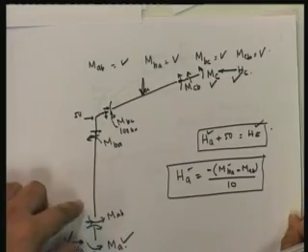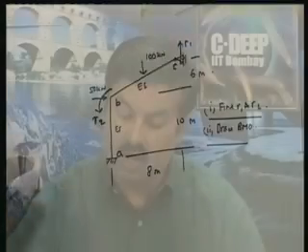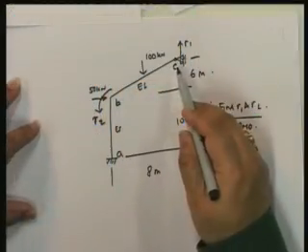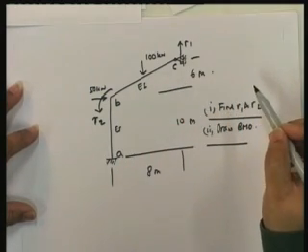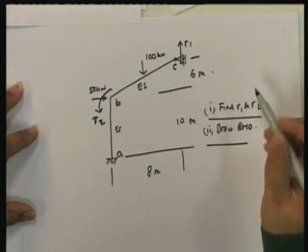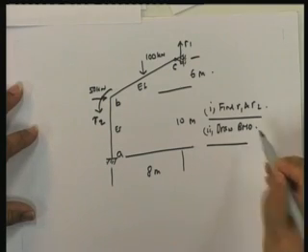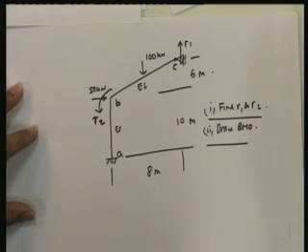So I am leaving you at the end of this lecture with two things to do. This is the first assignment that I would like you to do in displacement method. Please go ahead and solve the problems. First problem, having done everything, find out R1 and R2 and then draw the bending moment diagram using the procedure that I have outlined. Second, take this problem, solve this problem through, and find out R1 and R2 and draw the bending moment diagram. I am going to give you the answer to this and solve this next time.